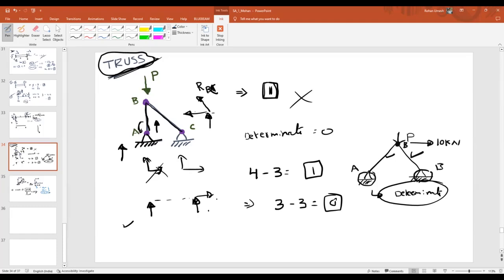Forces at support A will transfer through which member? So can I ask again? Through which element will reactions develop at support A? Through element AB, right or wrong? Yes, sir. Similarly, at point B, sorry, this is already turned as B, so let me say this is C. At support C, the forces will transfer through BC, isn't it?